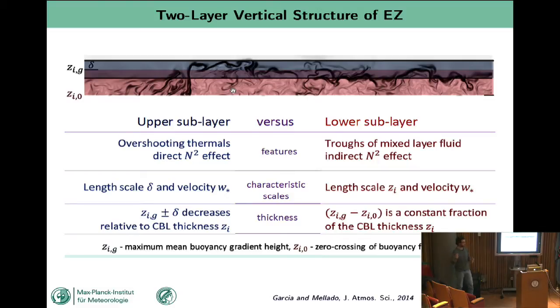So for the people in wall-bounded flows, one temptation is to think about it as an upside-down version of the near wall region, and you have the delta, which is kind of similar to the roughness sublayer, and you have this transition into the bulk. There is some work that tries to find some type of logarithmic or corresponding scaling in this region. I don't think we still have the accuracy to measure that, because it is really very, very heterogeneous compared to the channel flow or things like that. But there is some chance to look at things there. Anyhow, I'm talking too much.